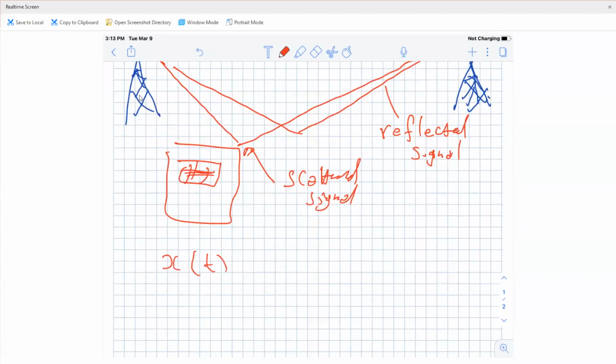Well, so we may imagine that at the receiving end we have the following. For example, x of t, we may have x of t minus tau, x of t minus, for example, 0.5 tau, x of t minus 2 tau. As you can see, the same signal x of t is sent and received by the spread spectrum receiver, but with different time delays. Of course, if you directly process such a signal, we will have weak signals with different phases. So the magnitude of the received signal will be reduced or become weaker, or in other words, we say fading signal.